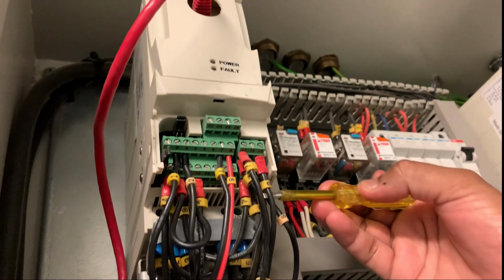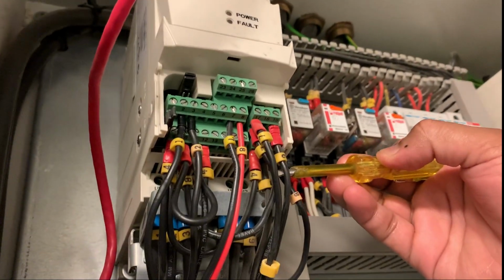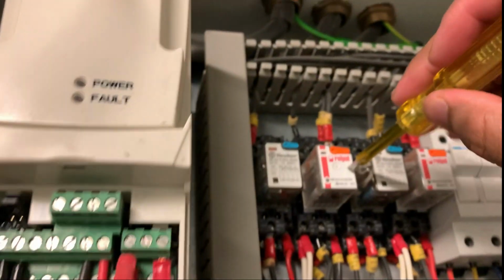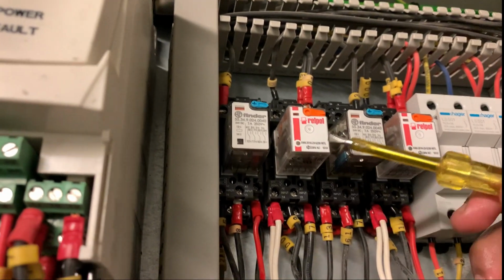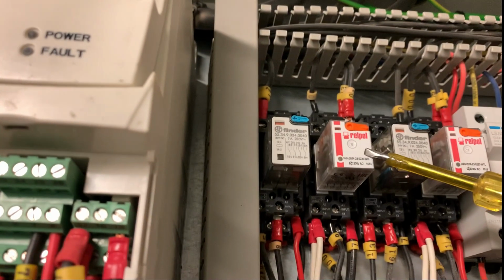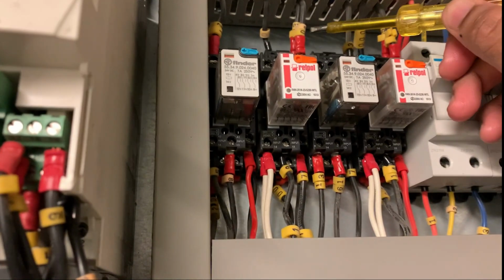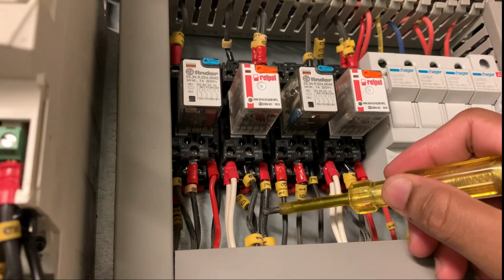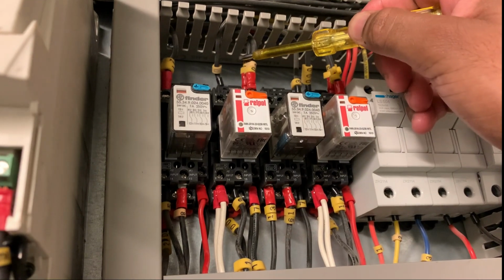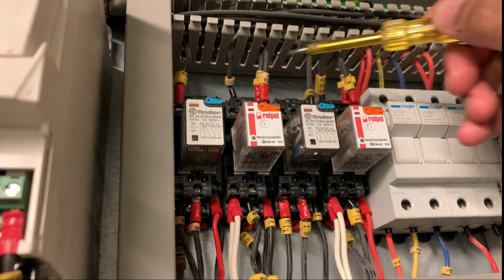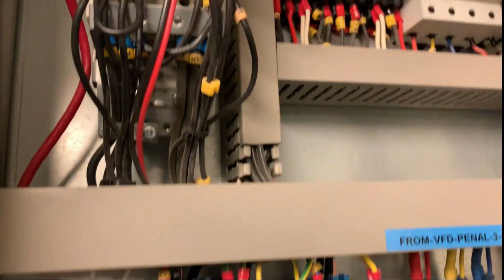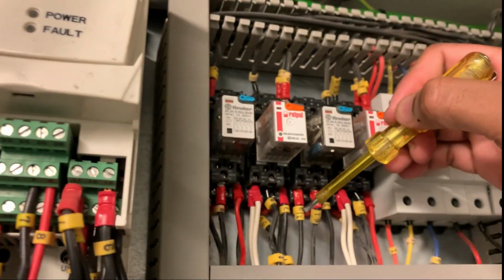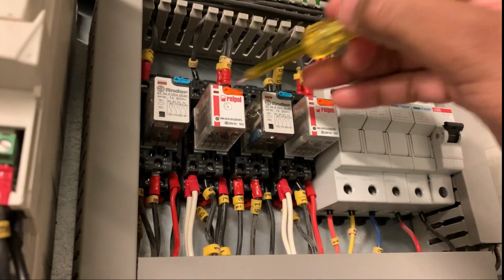Okay, and we connected a cable, number 9, and this number 9 will trigger this relay. As you can see, we connected number 9 over here. So when this relay gets actuated, we have also connected 2 more cables over here for the BMS, cables 7 and 2. We have connected these to our BMS. So once this contact becomes NC, it will show in the BMS whether the motor is running or not.